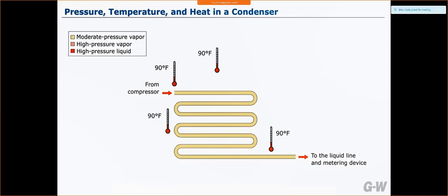But if I have 180 degrees, and that 180 degree difference to, let's just say, a 0 ambient temperature, well, now all of a sudden that heat's going to want to really leave very quickly because of that huge difference. So that's why places like Arizona, Nevada, they have issues with their refrigeration systems because the temperature outside gets so hot that the compressor really has to struggle a lot to get rid of all that heat.